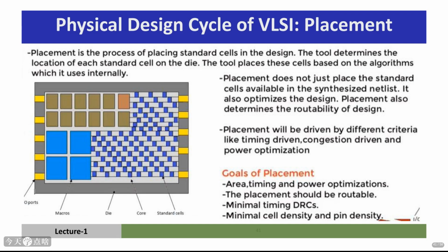Placement is driven by various criteria, such as minimizing area, meeting timing targets, or reducing power consumption. The diagram shows the typical layout of a chip using standard cells, with the core area filled with these cells, surrounded by macros and I/O ports.